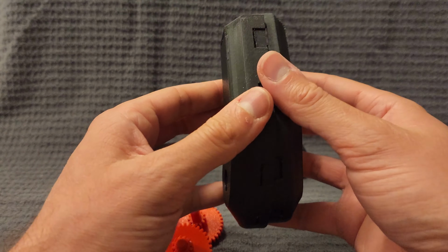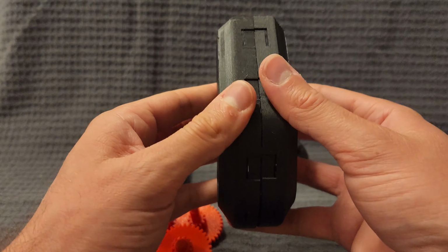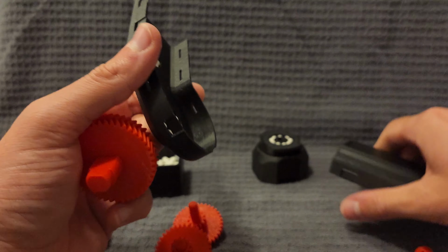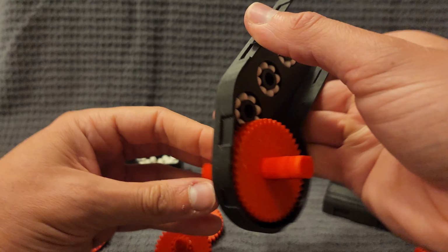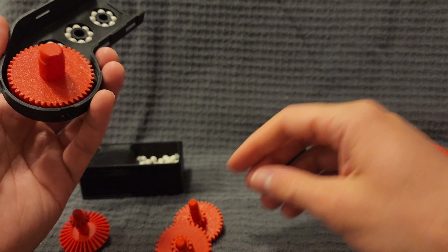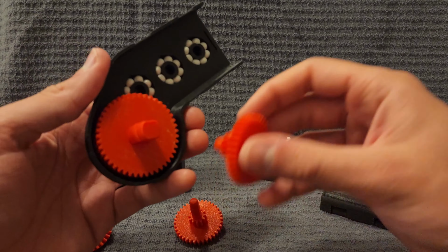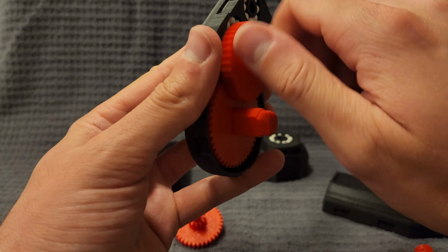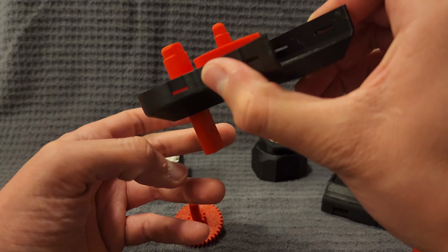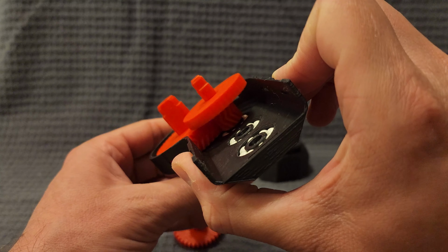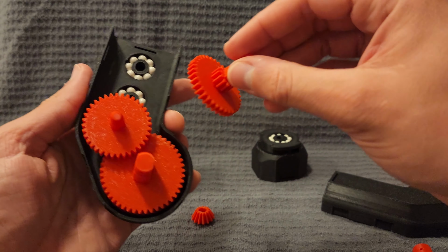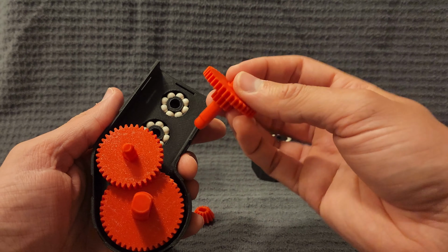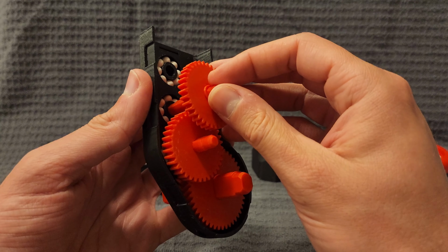Now let's assemble the two halves with the gears, and you gotta decide which side you want the gears to be, which side you want the device to be operated from. It's an ambidextrous design, so you could mount it on either side that you prefer. I want to crank it with the left hand, so that's why I mount it this way. So just insert all of the shafts, starting with the first one, the input shaft, and the second shaft with the herringbone gear. Make sure it spins smoothly as such. Then you can put on the third shaft, which will have the two regular spur gears.